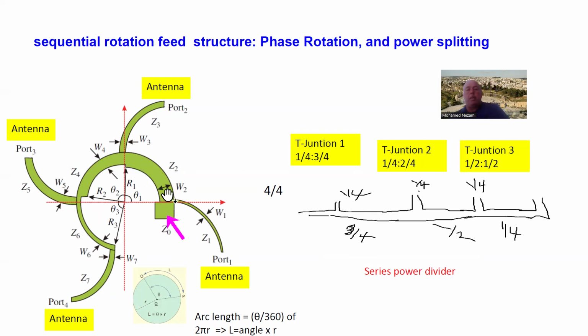Now, how do you figure out the length of these lines? These, of course, are circular arcs. They're pieces of a circle. And the way we define these is by using a radius with an angle to determine the arc length, and the arc length here has to be a quarter wavelength. As I showed here, this is high school level geometry. The arc length between 2 points on a circle of 2 pi r circumference is really the angle times the radius. So you take the radius and the angle, multiply them, and you get the length of this, and that's exactly what we follow here. We know how long it is because we know the frequency we're operating at, so we can figure out what the wavelength dimensions are, either in degrees or in millimeters or mils, and then say what the radius and the angle are that correspond to that.